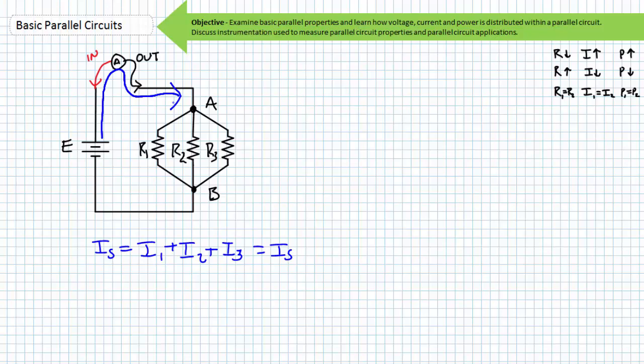If you think about this at the nodal level, node A has the ammeter outdoor and all 3 high leads of all 3 resistors connected to it. The ammeter indoor necessitated the introduction of another node, which I'll call A prime. A prime is connected to the positive lead of the voltage source and the ammeter indoor. Notice that node A and A prime are not the same node.